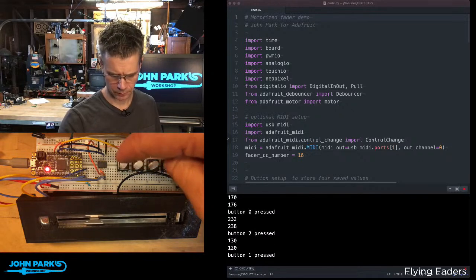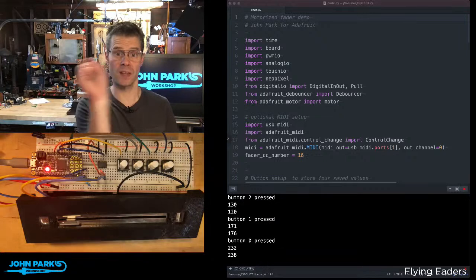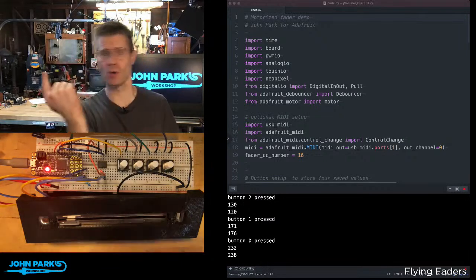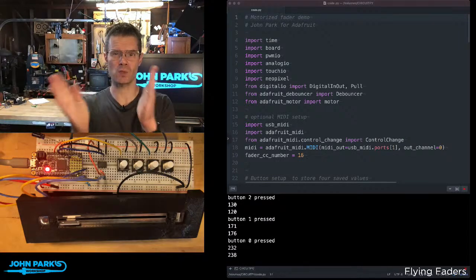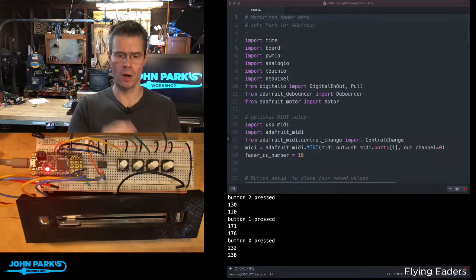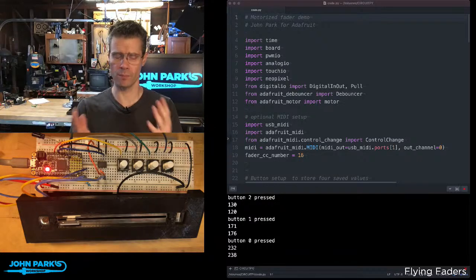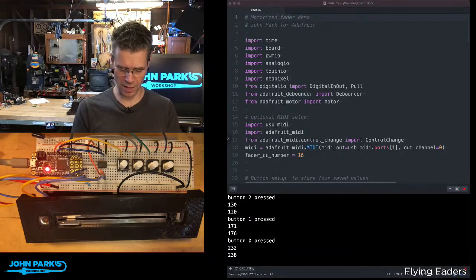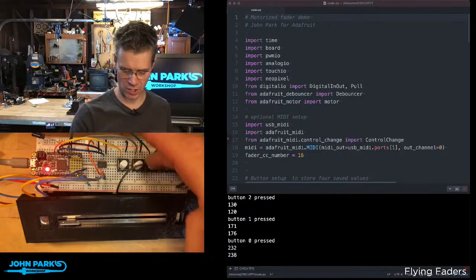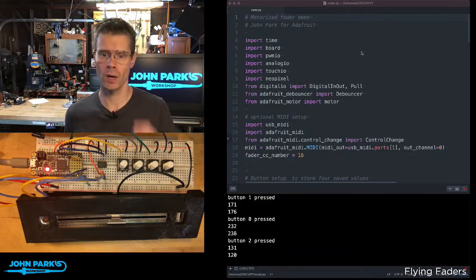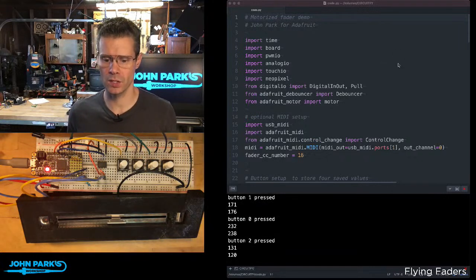But essentially, I was running into these overshoots, and then you can get into these real jiggles where it just keeps overshooting the mark. So you can widen, that's why I have a slop of about 2 positions. You can widen that or use other sort of PID types of algorithms in your code to get there without blowing past it. So let's take a look at the specific code that I've got going here.